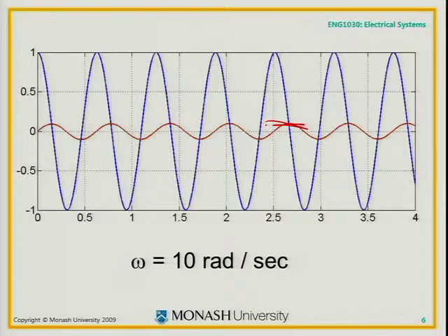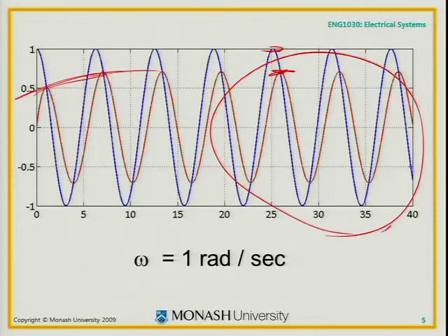So this one isn't particularly fast because it only has one element. If you put more elements in the right way, more capacitors and inductors, you can make fancier filters. You could put op-amps in there if you wanted gain as well. If I wanted a gain of 100 at the start instead of a gain of just below 1, well, I'll just put an op-amp in there to give me some amplification.